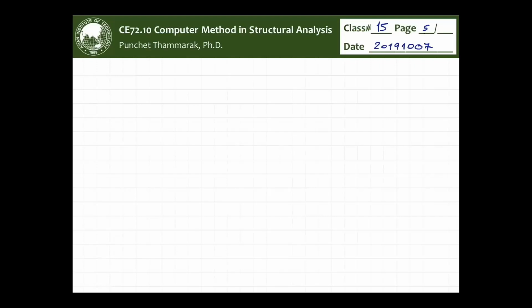And you plot the graph, and you also document that table of stability function. When you print out the table, you don't necessarily have to print the values of gamma, beta, because it is useless. You just need the S12 and so on.